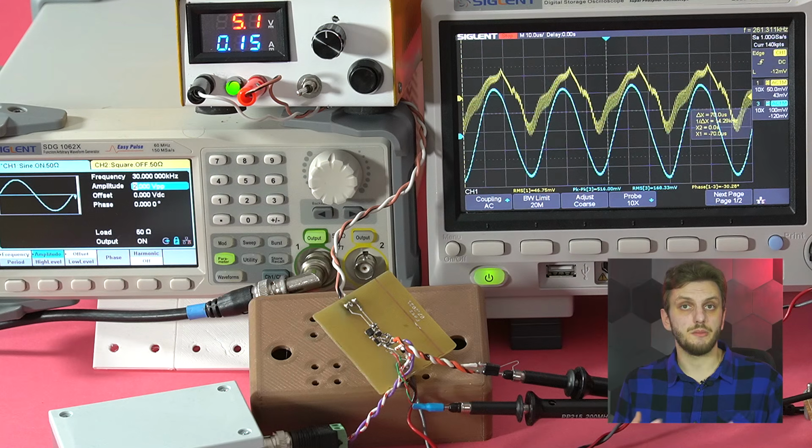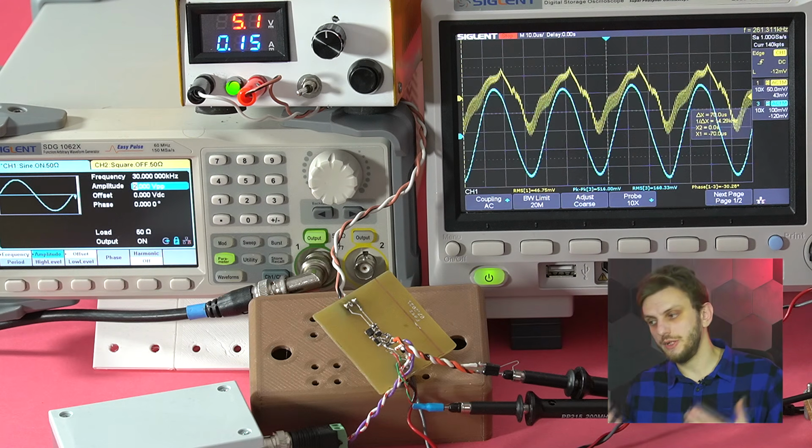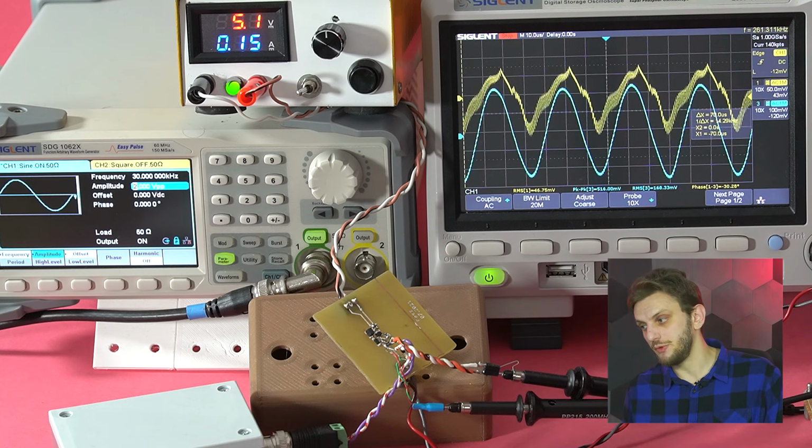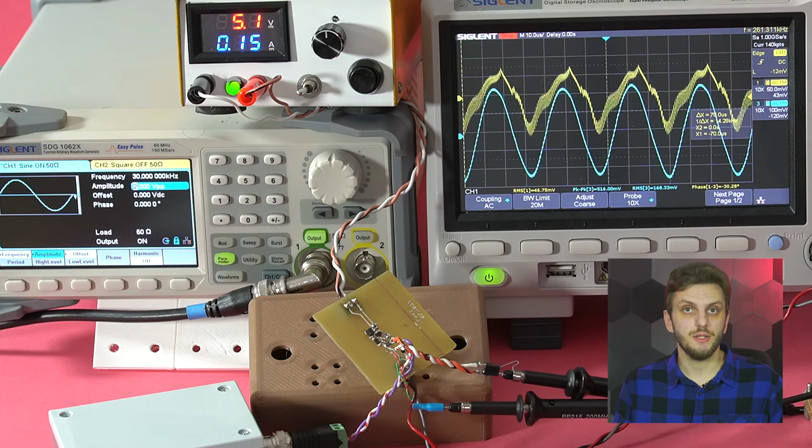Now, another point to make about this injected signal is that it will usually be different for different frequencies. So at relatively low frequencies, the power supply has a lot of gain, so you will be working with larger signals. As you move to high frequencies, the gain drops, so you will be working with slightly smaller values.